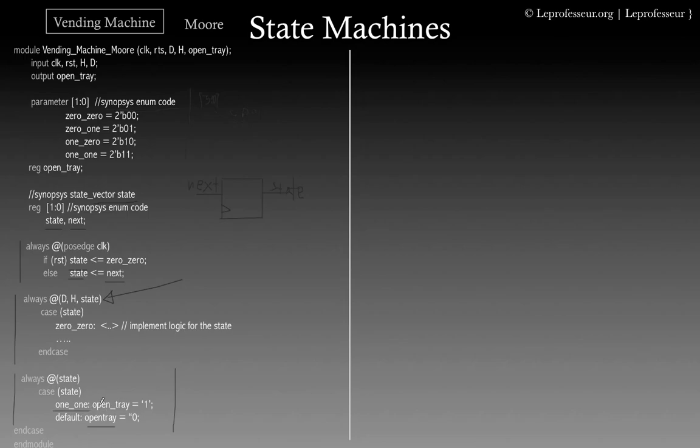You would output in the state 1 1, that is 1. Okay, and the state is going to change on every next clock edge. So you're going to receive the output on the next clock edge when the input changes. So that's a difference in the Moore version of the machine.